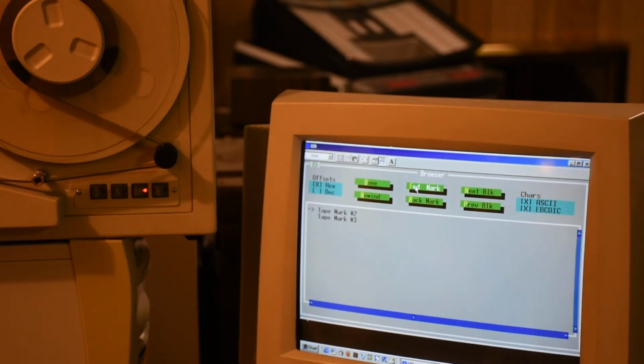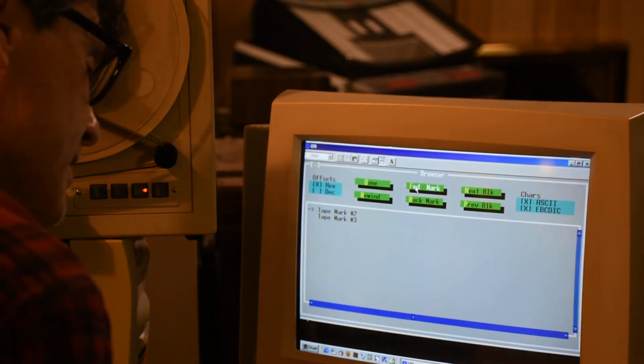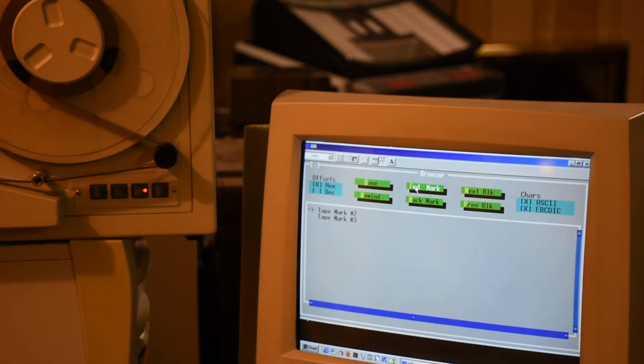Because it is a streaming unit, it's not a block writer. So to pseudo block write it, I would have a fixed block size and then write those bytes. So that is a way to control this tape drive. There's 34 lines that need to be connected, and this Arduino Mega 2560 has 54 lines, so it's absolutely perfect as a tape drive controller.